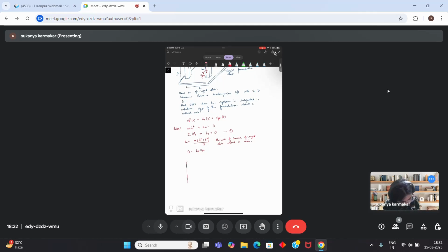Suppose this is the slab and I'm looking at the slab from the top, right? I have to find its stiffness. How is stiffness defined? So the force required to provide a unit deformation, keeping all the other degrees of freedom zero. Here, all the other degrees of freedom are not there, so it's zero. So you have a slab like this, and I will provide u theta is equal to 1. That is, I will rotate the slab.